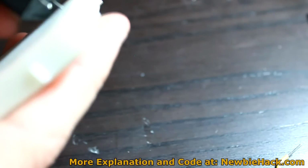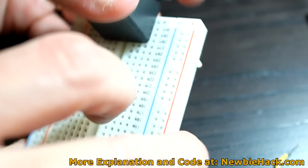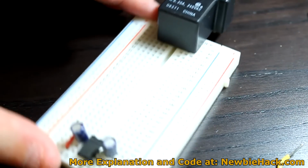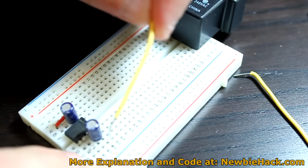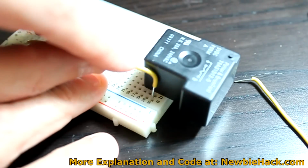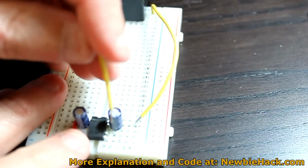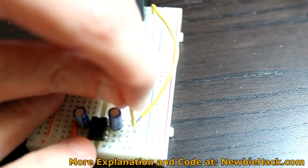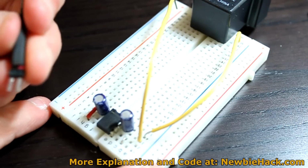To test to make sure that this relay is working, I'm going to plug this into the breadboard, and I'll just use the first pins here. And the pins are on either side of this breadboard, so they're not connecting. And I'm going to run the output, the 5 volt output, to one side. That'll be here. And then running it to the other end, and the pin is located on this strip. And then I'll take the ground, which is the next pin down here, and I'll put this on the other side. Actually, I'm not going to connect it yet. I'm going to show how it responds when I'm connecting it and disconnecting it.